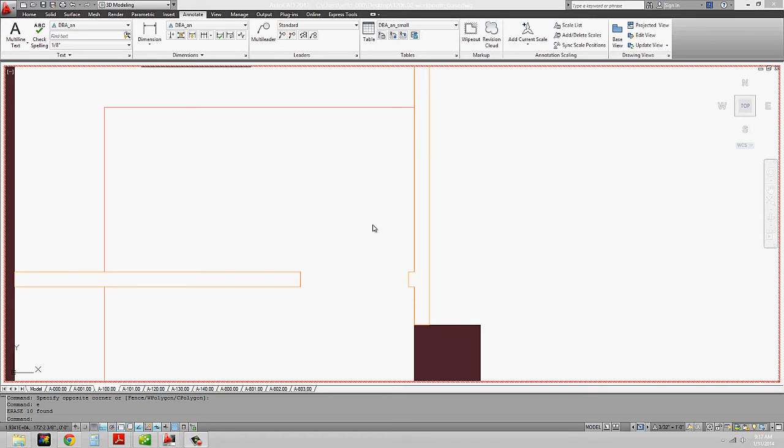If I do a polyline, okay, you'll notice that my background is white in AutoCAD. Some people do like to work with a white background. AutoCAD throughout the years has kind of been playing with the color of the background. So you will find that some people use white, some people use black, okay, as with yours is a blackish color, and you can change it in the options. So if you feel like you want to play around with that, that's one of the display options in the options menu.